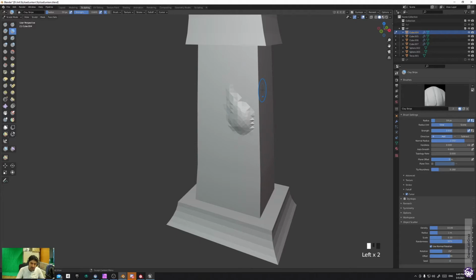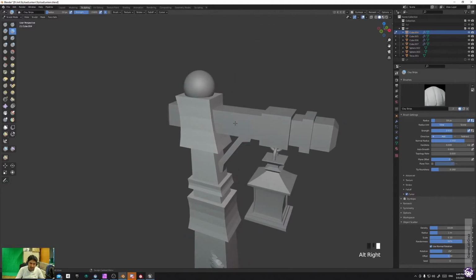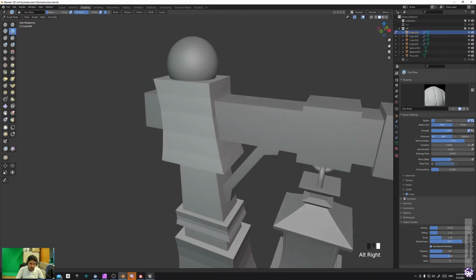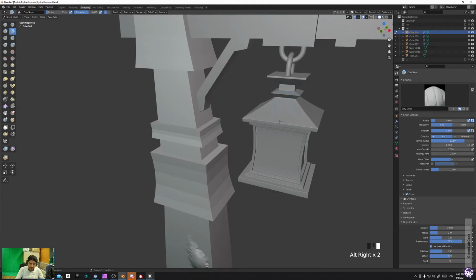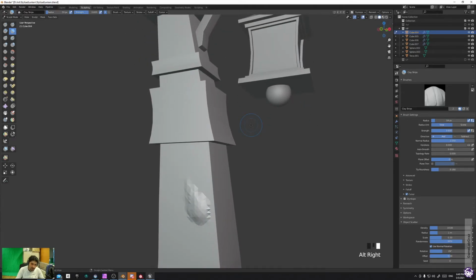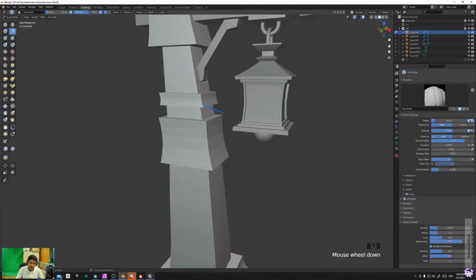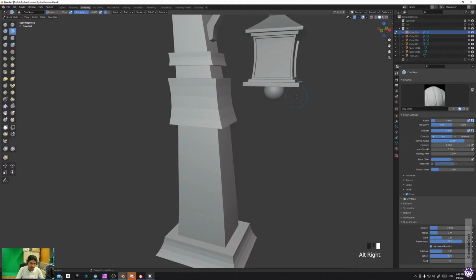For this type of sculpting, I would like to separate the objects, because later on you can go into Substance Painter and bake according to the name of the object. If you have separated objects, you can bake better, because there will not be any smoothing between two parts of the objects. All parts will be separated. Otherwise, if you are sculpting, for example, a human body or something that has smooth connections, you can join your objects. There is also a remesh tool recently added in 2.83, I think, that lets you join your objects using the voxel remesh or another method.